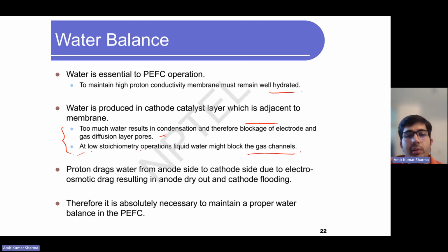Protons drag water from the anode side to the cathode side due to electroosmotic drag, resulting in anode dry out and cathode flooding. This is also a case. Therefore, it is absolutely necessary to maintain a proper water balance in PEFC. So, proper water balance is important in PEFC.